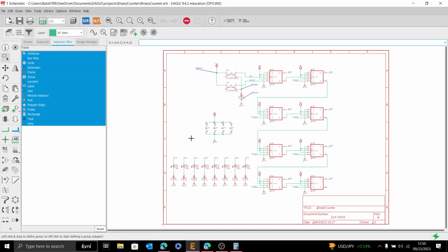If you look closer at that board, you'll see in between those two buttons, I took a razor blade and scratched away the trace. And then on the bottom, I added a resistor for the pull down, and it worked.